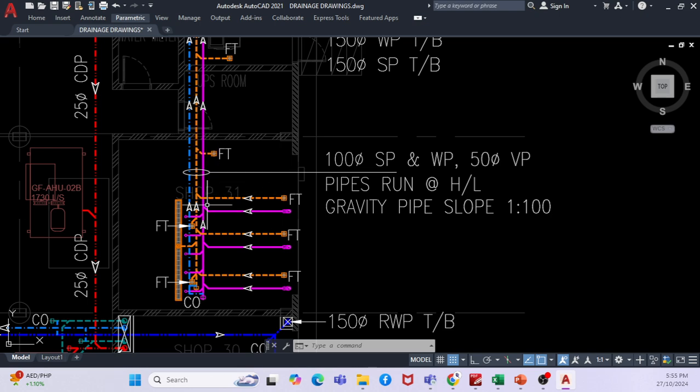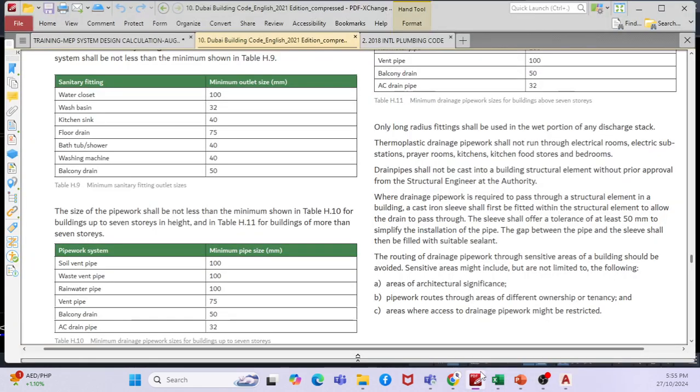So this is the calculation as per the DFU. Based on the DFU calculation, I will find out the pipe sizes. What are all the soil pipes? When I say soil pipe, I can connect WC and also the urinal, right? So I'll be connecting all the urinals here. Okay, so if I go to my IPC standard,